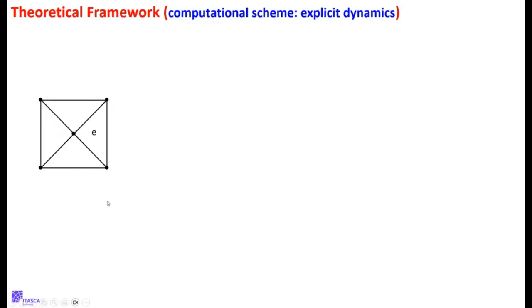So we start with an element, and what happens? We have these things called nodes, and these guys can move. And basically, as these nodes move, they stretch the element or they compress the element. And so we're constantly taking small steps in time. We load somehow, we take small steps in time, and we keep updating these stretchy forces. And notice this node, this is the amount of force that the node is applying to the element. Like, think of the elements pulling back with that much, given a displacement. Well, this node also has an answer for that, and this one and this one, so you sum everybody up.